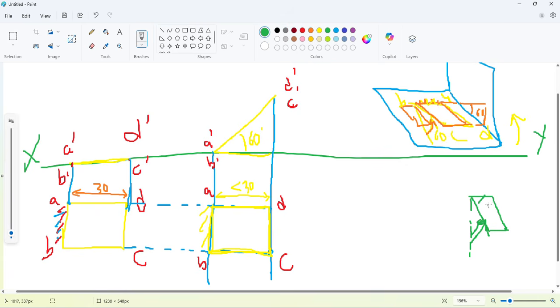Okay, so now this is the resting edge, so now you have to rotate it in such a way that this surface is going to align with the VP. So now what we have to do, just need to rotate this thing. Right now this edge is parallel to VP, or to the reference line. So what we will do, just rotate this thing like this, either this way or that way, at 45 degrees. So with this reference line, the surface is going to be aligned.